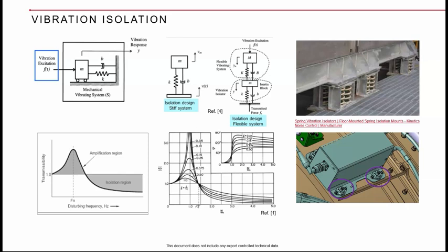the spring soft mount, we call. So these mounting springs are elastomeric mounts for softness, or you take viscoelastic materials as damping elements, again along with the vibration isolation background. Okay, so you design it in such a way that you have your natural frequency at 1 by root 2 times this point. So if you say this is your operating range, then you keep your natural frequency of the system along with the soft mounts.